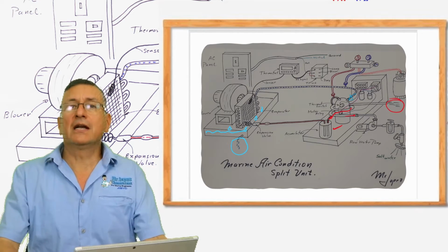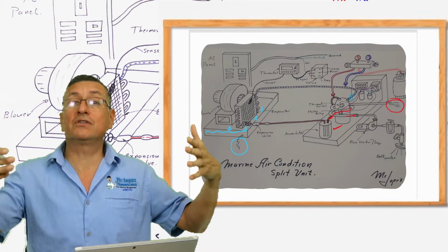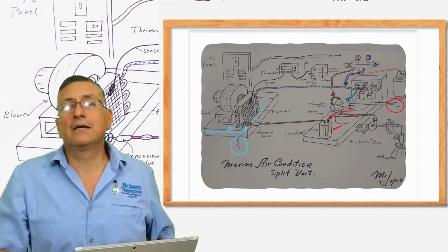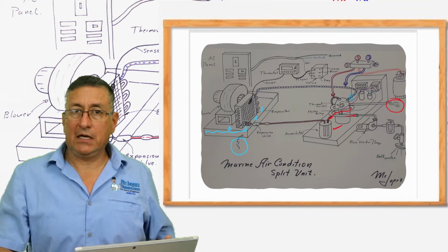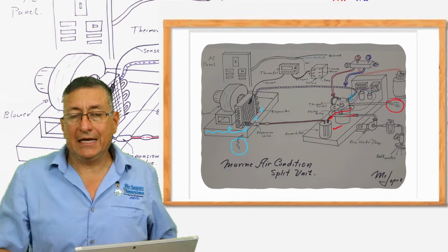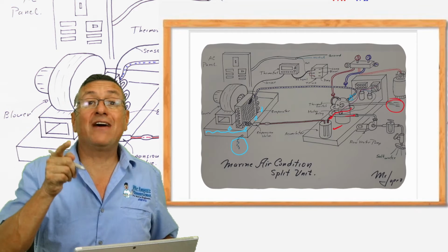Once again, my friend, remember, we are going to talk later about that, and we are going to do the process to remove heat. The enemy of the refrigerant is the humidity. The enemy of the refrigerant is moisture. Yes, and we are going to try to remove moisture from the system with the vacuum pump.